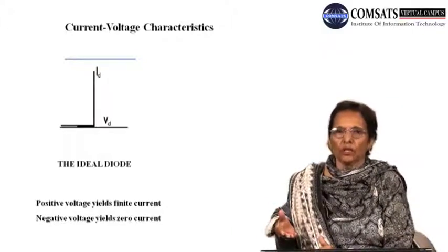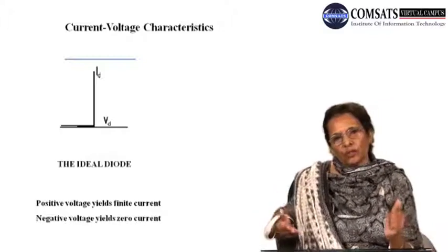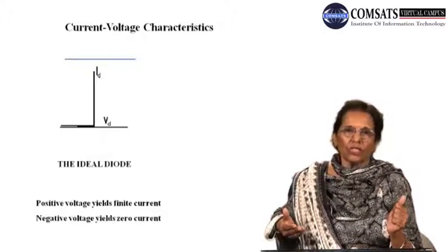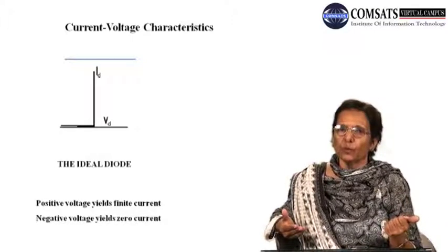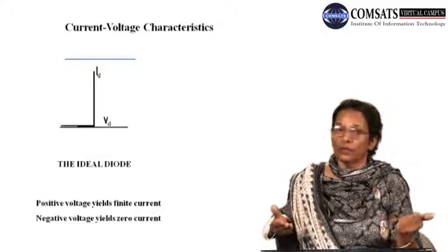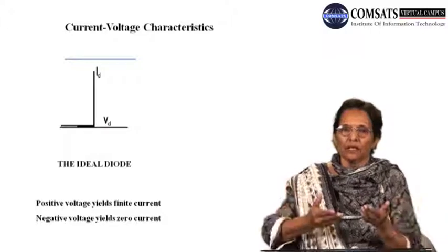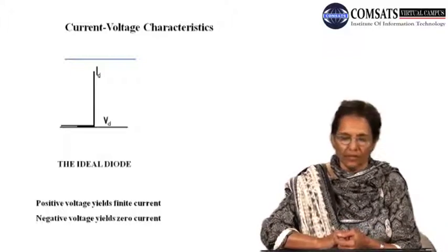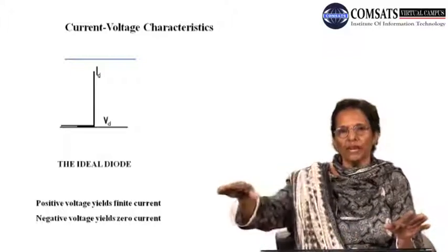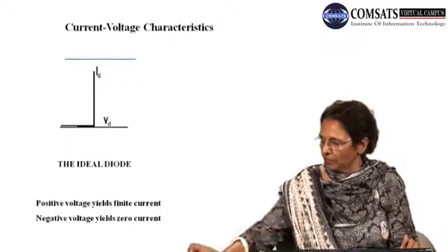Very small, about 1000 times smaller than the forward bias current. And because the number of minority carriers in the diode is very small anyway, this current would be small and it will be saturated, because whatever minority carriers there are on the N and P side, only those can drift, and hence the current would be saturated and negative. Therefore, you see an almost flat and negative current in an idealized PN junction.